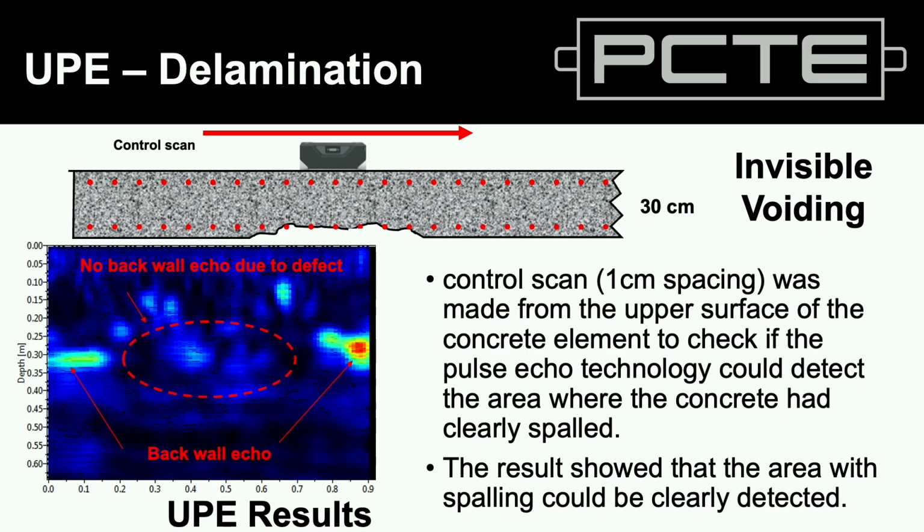So sometimes if your surface is rough, like a spalled underside or some sort of damage that doesn't give you a flat surface to bounce the signal back to the sensor, we find our result being scattered data. In this case, illustrated quite nicely, it's a spalling underneath an element, which we detect not by having the element look thinner, but by the reflection of that thickness vanishing.